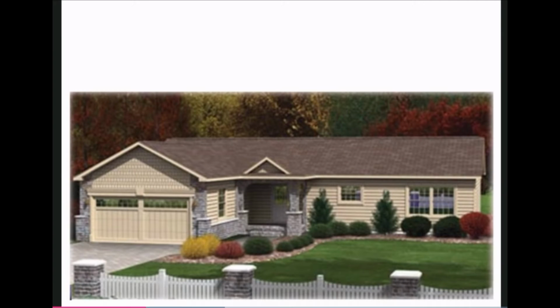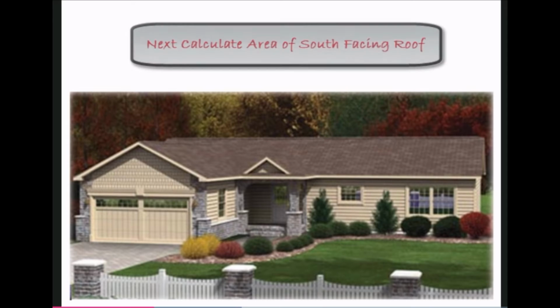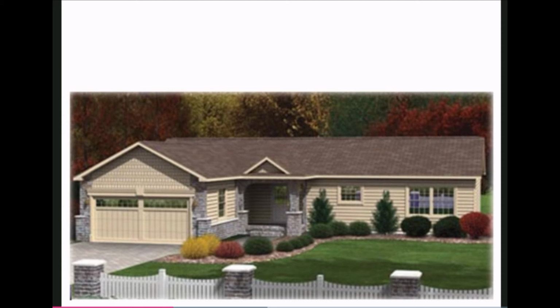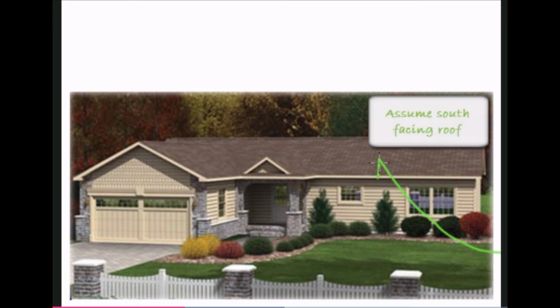So to determine the amount of solar panels required, we need to calculate the roof area of the house, and we'll focus on the south-facing roof for this house. This is a picture of a typical ranch-style home, and we're just going to make the assumption that this roof faces south.